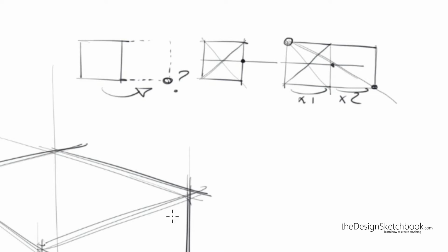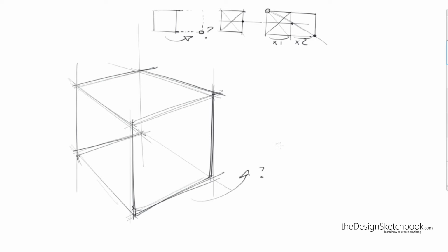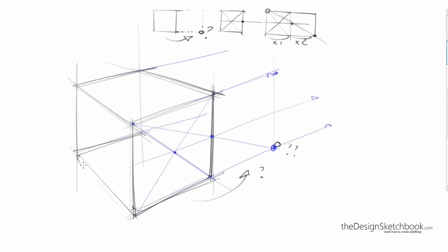So here is 2D flat from front view, and it happens that this geometry is actually applicable in perspective as well. It's pretty magic. So the two diagonals, I prolongate the line, which is going to go to the vanishing points. This one follows. I get this dot, I connect to the corners, I prolongate it there, and by magic I just draw a vertical line right here. Okay, and then you get this projection of this cube exactly the same in perspective, side by side. And then I'm going to project this front view to the back part of the cube.